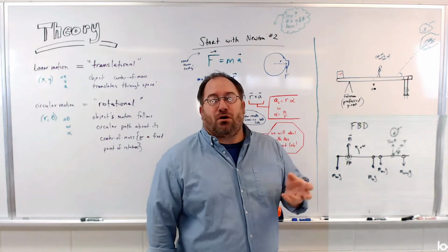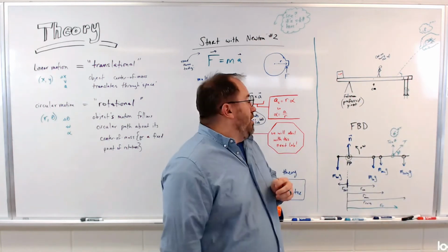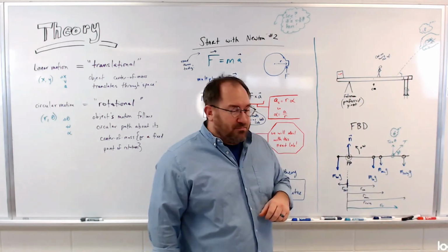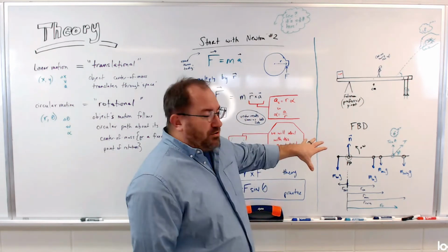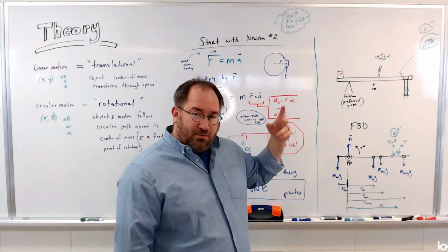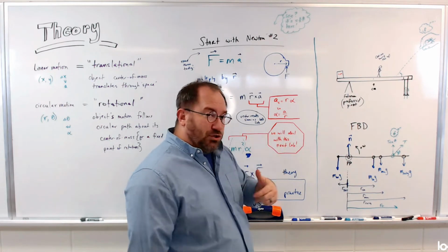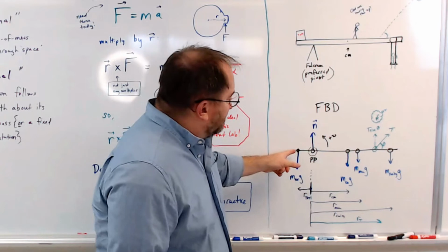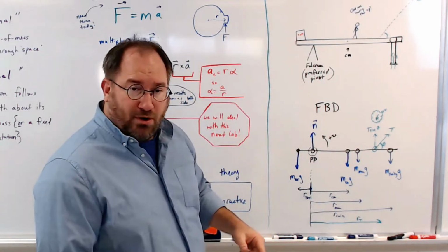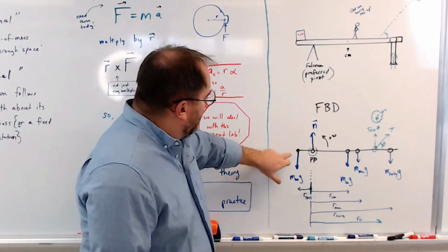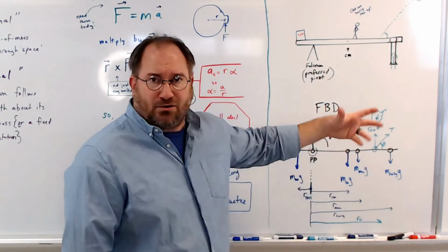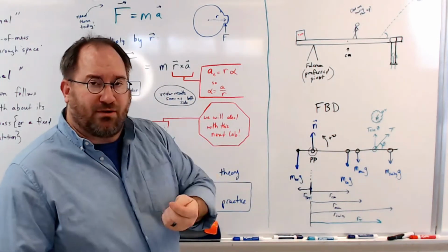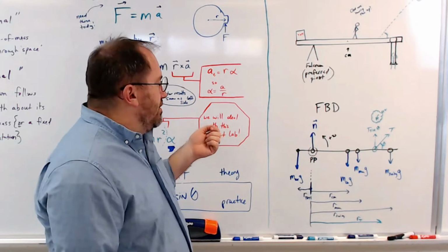When you draw your free body diagram for this, you want to be more careful about where you place everything, but you do want to make sure you have everything in place. So we write down just a straight line for this board, and then we put a mark of some sort, a dot or a circle, to mark where everything is relative to each other.